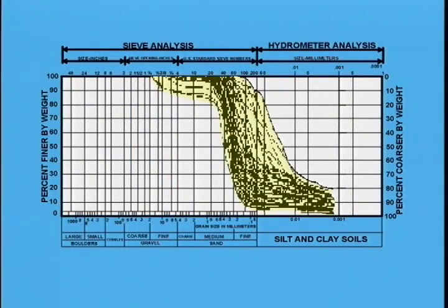This is the range in gradation of the outwash sand. Material coarser than the number 20 sieve practically always is less than 10%. Generally, material finer than the number 200 sieve amounts to 5 to 35%. Occasionally, larger amounts occur. Because of its very small percentage, the plus 20 sieve material occurs as float in the rest of the material and has no significant effect on the characteristics of the material. Generally, the gradation curve of the minus 200 material is very flat. At least a 10-time change in grain size occurs for a 15% change in percent finer. Because of this flatness, the coarse fraction does not at all act as a filter for the fine fraction.